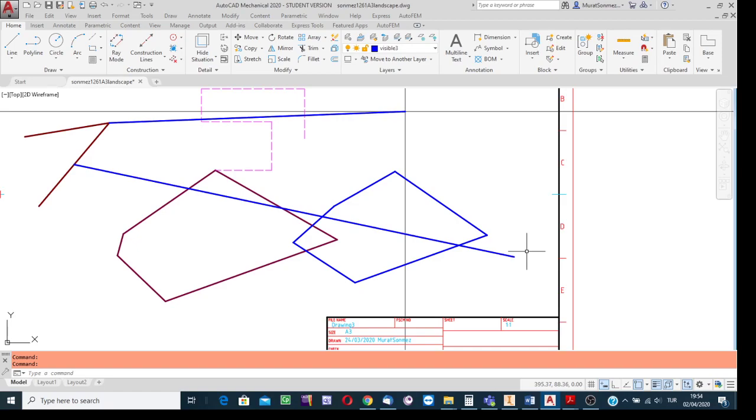But now at present the line has been freely, arbitrarily extended. So what is the thing to do after this stage? Start the trimming process. Use the trim technique. Click on this button, start the trimming process. Press the enter key. Yes, it is a trick to be able to trim the unnecessary parts. Don't forget, click the trim button, start the process, and click the enter key. And then indicate the unnecessary part, this further extension. Yes, partially raise it and then press the escape button.